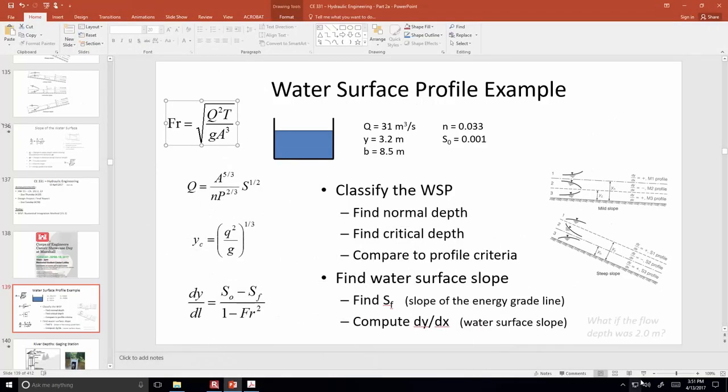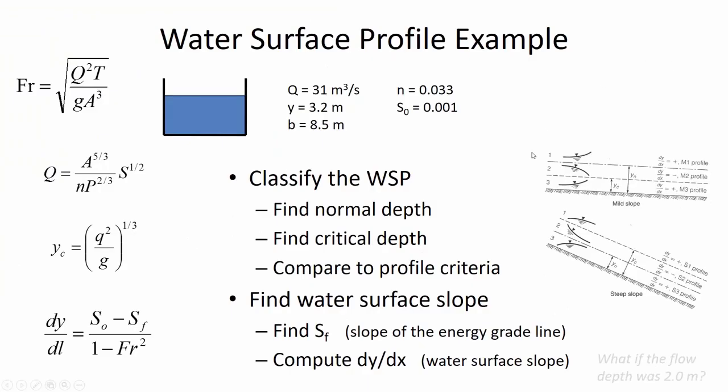Let's go back to the water surface profile sketches. These typical diagrams say that in zone 1, you see the little drawing here shows that in the direction of flow it's getting deeper. That's what this is meant to convey. And it also says dy dx is positive. So everything lines up as we would expect. It's getting deeper in the direction of flow.